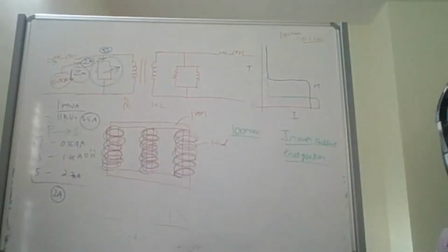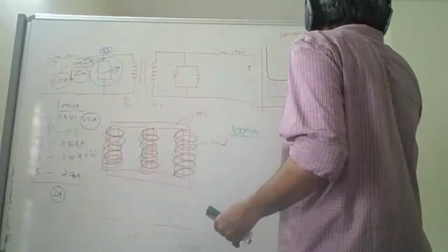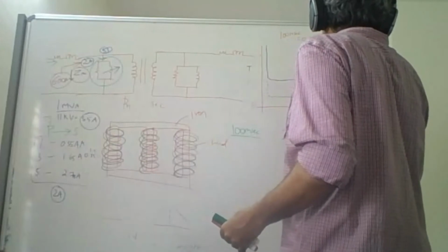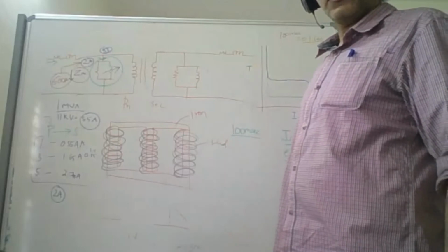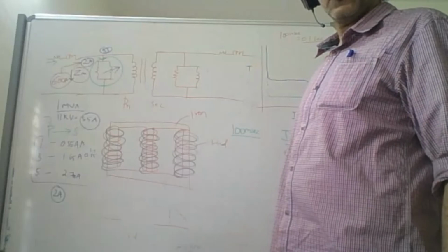I want you people to actually go through and share. If you have gone through any type test report, please share it only with that particular sheet, then we can go through it. So in that time versus current curve, for the M, you have written M. The bottom curve is the transformer, yes, you are correct. But then the current will be much lower, no, sir. 100 milliseconds means it will be almost hugging the line. It will be almost invisible compared to the motor, no, sir.